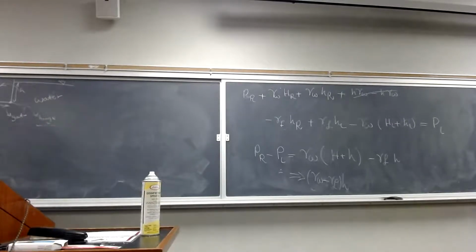And the hydrostatic pressure on the horizontal side creates a clockwise moment about the hinge again. We want to find the net clockwise moment. So sigma M clockwise. This is the question.